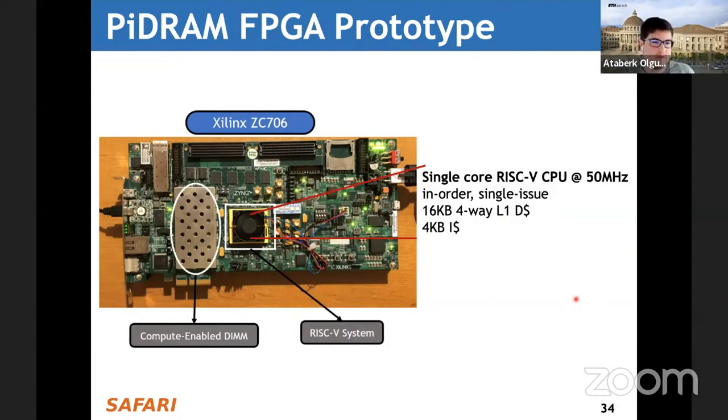But all of these works, I think, assume that there is a linear relationship between the physical address bits and the DRAM address bits. That basically means that multiple bits are XORed to form one bit of the DRAM address. But if this assumption is broken in future generations of processors, then it will be more tricky to reverse engineer that. And maybe if the vendors wanted to, they could make that information more proprietary, but that would work against what you discussed.